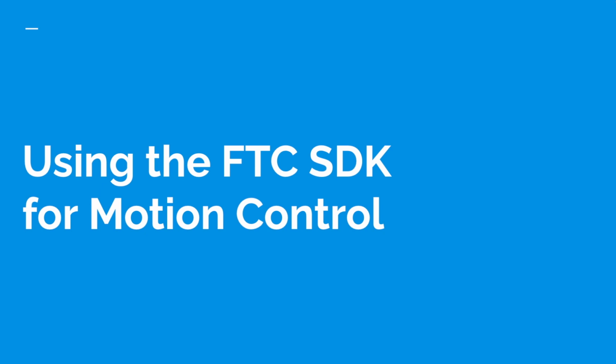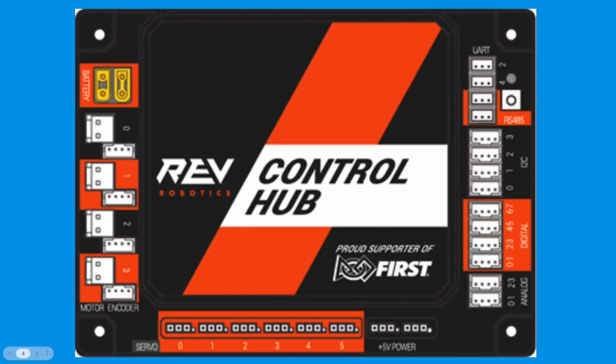So, to start, what you want to do is plug in your motors into the control hub. The control hub looks like this, and there are many ports on it. These ports right here are for servos, these ports right here can be used for sensors, and these ports right here are for motors, and this port right here is for the battery. So you want to plug in your motors into these ports.